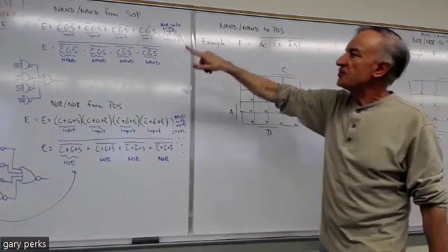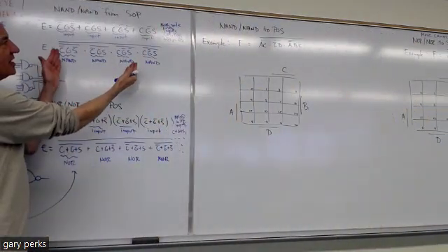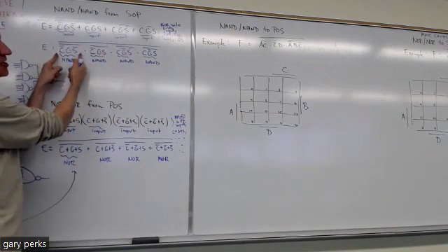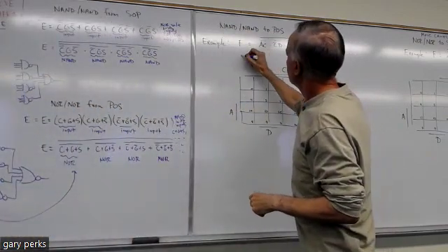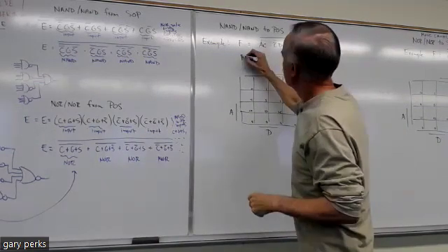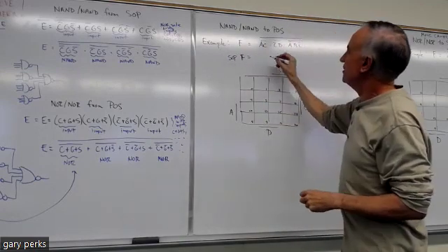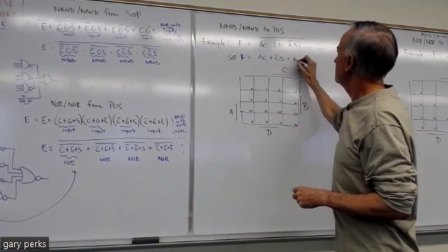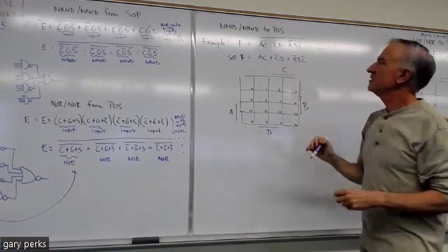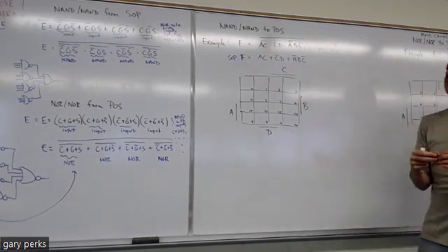So as I was saying before, if you look at our example here, to go from NAND to SOP, you're just taking what's underneath the bars and pouring them together. So this would be the SOP for F. It's just going to be AC ORed with not C D, ORed with not A, B, not C. I'm just taking what's underneath the bars and pouring them together.